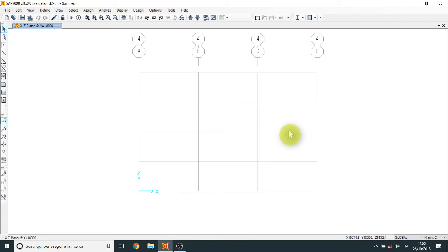That means L that is 40, 40 and thickness of 3. Pay attention to the local axes and the principal axes. If this is the centroid and these are the X and Y directions, the principal axes are rotated by 45 degrees.